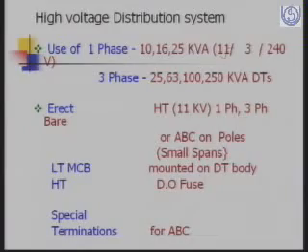So we now prefer to go in for the high voltage distribution system. The high voltage distribution system differs from the low voltage distribution system in that we use small capacity transformers and have less of LT, or LT-less, because it is very difficult to have no LT at all, so we call it a less-LT system, where the transformer is of very small size, 5 kVA, 10 kVA or 16 kVA, and a few consumers, maybe 3 or 5 or 10, are connected to